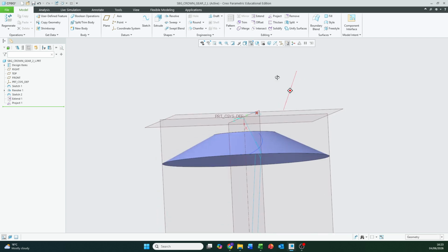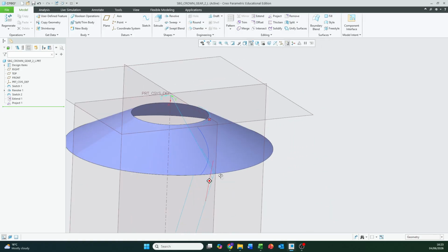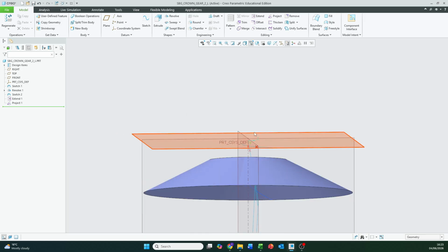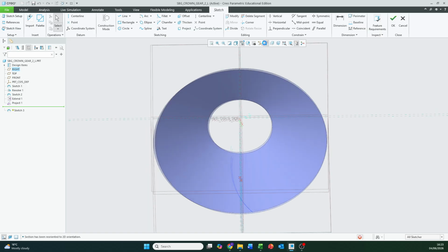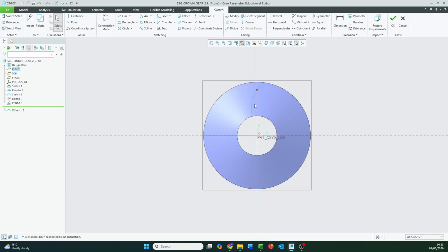Okay. Right. Next up, we are going to, again, use the pattern tool to move a copy of this curve to be directly in line with our initial geometry here. But to do that, I need to understand the distances involved. Let's go back to a left orientation.